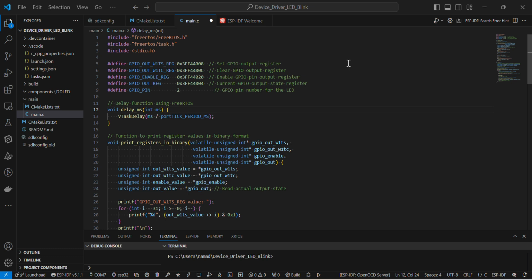The same LED code, but in a different way, we are going to see. Actually, it is kind of device driver level development. Before that, what we saw is that we are directly using the gpio.h file. So we are directly calling the function, and inside the function, gpio set, gpio pin mode change kind of thing, we are calling automatically. We are setting that using the macros.